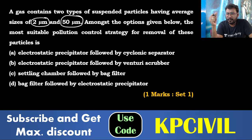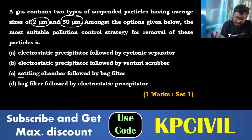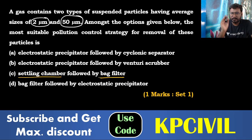Electrostatic precipitator followed by cyclonic separator? No. Actually, first cyclonic separation will be done, then electrostatic precipitation. Second one, electrostatic precipitator followed by Venturi scrubber? No, Venturi scrubber is not considered for this. Discard it, reject it. Settling chamber, yes, this is gravity settling chamber, followed by bag filter. Yes, correct, it perfectly suits.